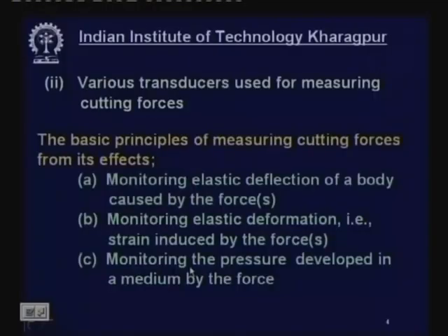So these are the basic three principles used for measuring the cutting force based on its effects. One is elastic deflection, the other is elastic deformation like strain, and the other is pressure, which can be measured directly by a pressure gauge through a liquid medium or gas medium, or through a sensor which converts pressure into some electromotive force or voltage, like that.